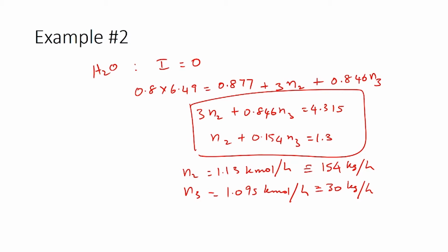So, the solution would contain sodium acetate and water, and based on the mass fractions we can find the average molecular weight and use that for calculating the mass of the crystal solution which is leaving the system. So, these values give us the total mass of the components which is leaving the system. So, you would have the rest of it leaving as water vapor. So, that would give us the total balance for the mass.